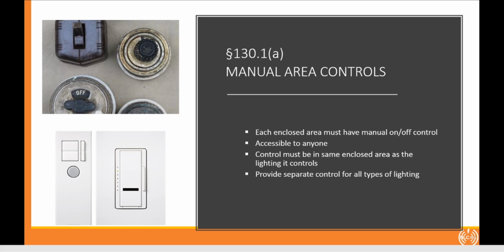It can't be a switch that requires a key to operate it. It can't be a switch that requires a passcode, passkey, or punch-in requirements. It's not a switch that is in the form of a remote that sits on somebody's desk. That would not qualify as a switch that is accessible.